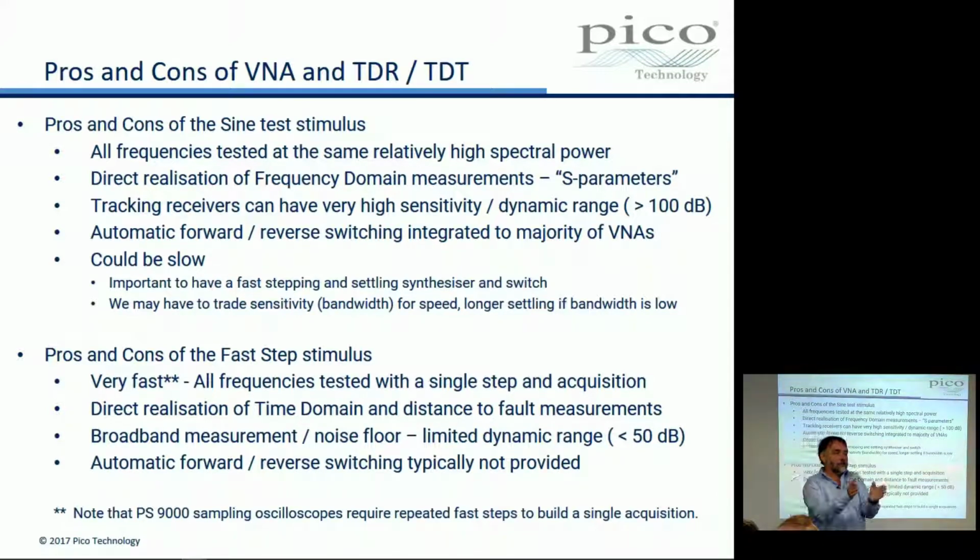So if we're going to measure something in a 10 hertz bandwidth, the amplitude of the signal for instance, then we're going to have to wait for 0.1 of a second before it settles so that we can make a measurement. So if we put the bandwidth right down low to get really deep noise floor, then we're going to have to slow the sweeps down, otherwise the sweep's going to go too fast, right? So the VNA automatically adjusts its speed to the bandwidth settings. We'll see more of that.